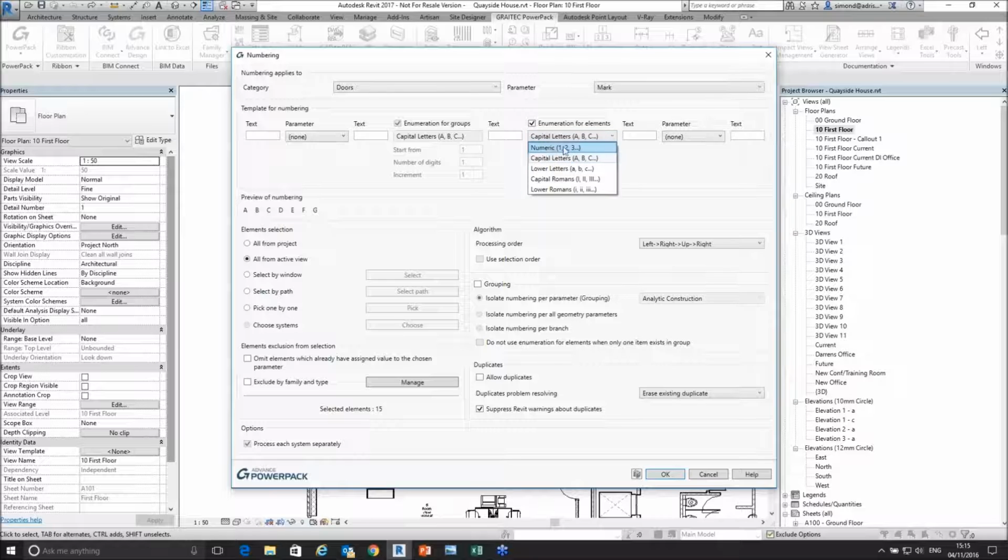So if I actually had numeric, I could set that to 001. Yeah, and we can start to look at setting that up, what the increment digits are. It'll increment by 1, and what the increment is as 1 as well. Okay, so I can control, yeah, so there we go, increment digit 2, if I wanted it 3, that'll give me doors 001, 002, etc. I could even then say, well, actually I want to increment that by 10, and then it will keep the 1 from the first one because my starting character is 1, and it'll add 10 to each of the doors as well. So the sequencing and the way that we can work in here is incredibly powerful.